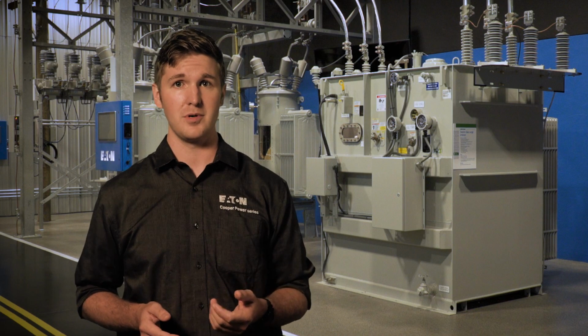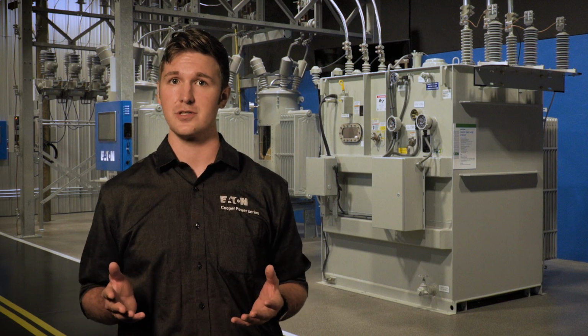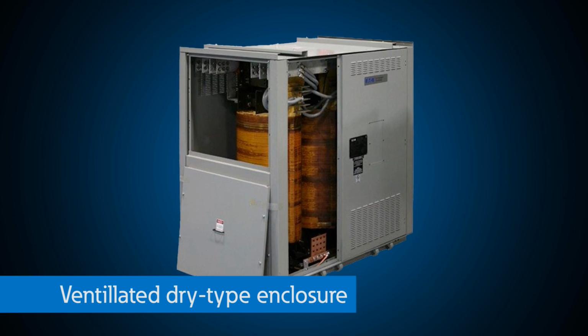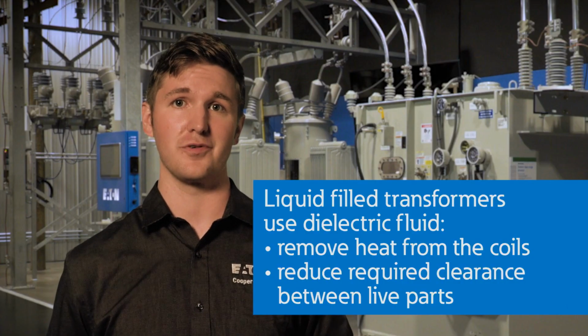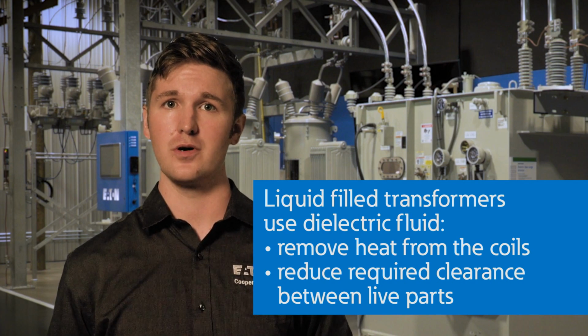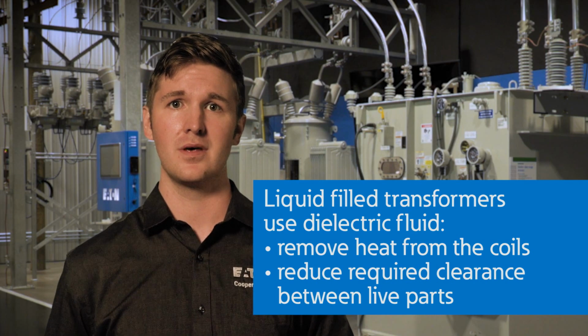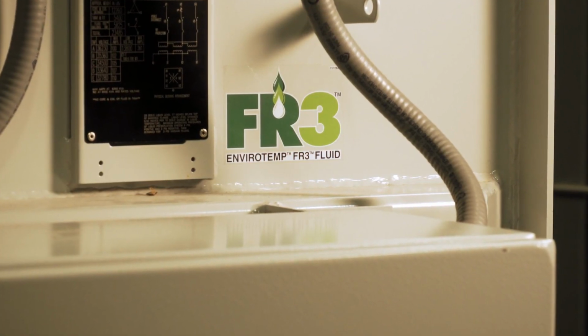For dry-type transformers, the construction is nearly finished. The core coil assembly must be installed in a ventilated enclosure and the appropriate terminations added. Liquid-filled transformers utilize dielectric fluid both to remove heat from the coils through convection and to reduce the clearances between live parts. Modern liquid-filled distribution transformers are filled with biodegradable natural ester fluid like FR3.